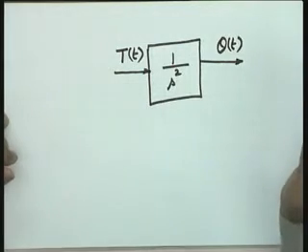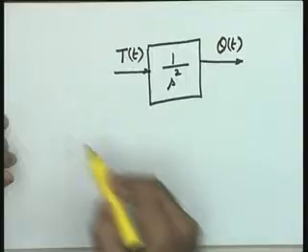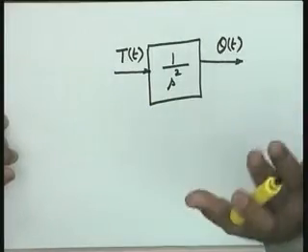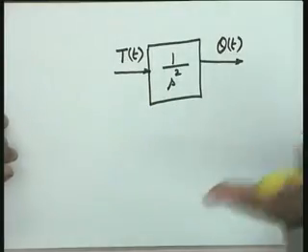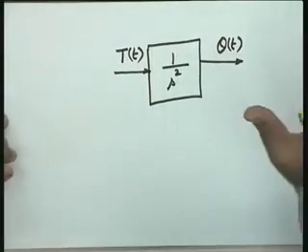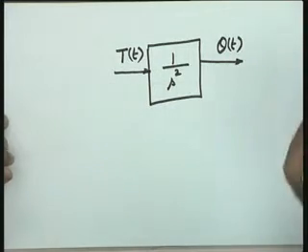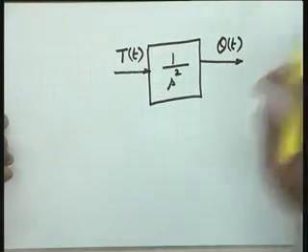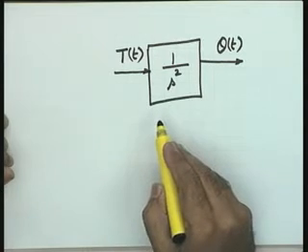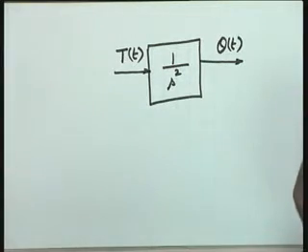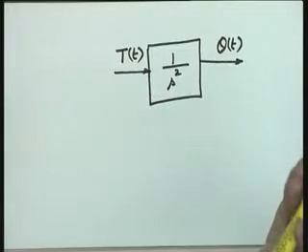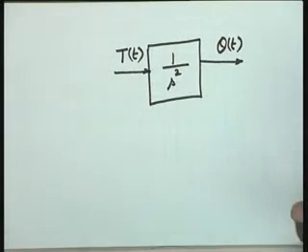The steady state performance of this system when the loop is closed is going to be satisfactory, is going to be good, because the steady state error to step inputs will be 0, the steady state error to ramp inputs will also be 0, and there will be a finite amount of steady state error to acceleration inputs, this being a type 2 system. You see that when you are given a plant, some initial comments you should be able to make right at this particular stage itself.